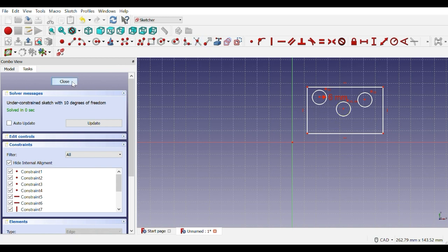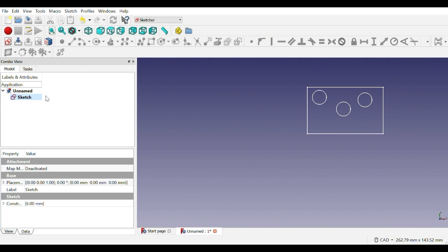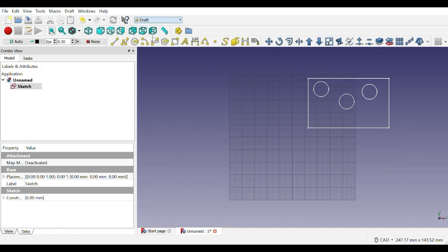Now let's close. You've got to always close these things. Now I want to create clones, and you can't do that in the Sketcher. You've got to use the Draft mode. Or I don't know if you can do it in the Sketcher, but the Draft mode is what I found. So what you do is you highlight it here and then click the little sheep. It creates another one. Okay, now where'd it go? Well, it's underneath this object here, so let's move it.